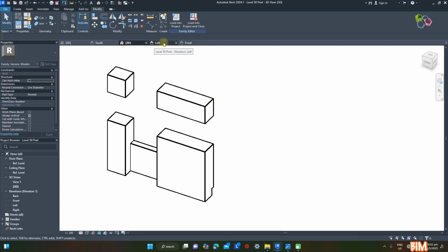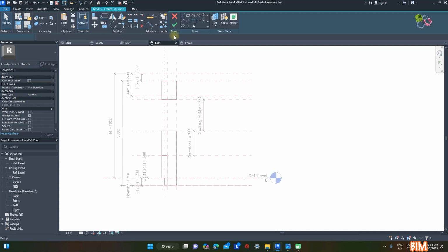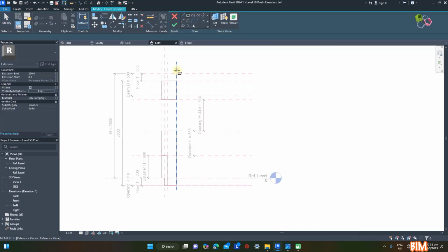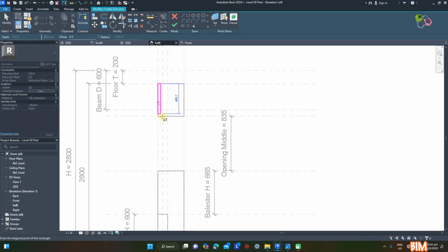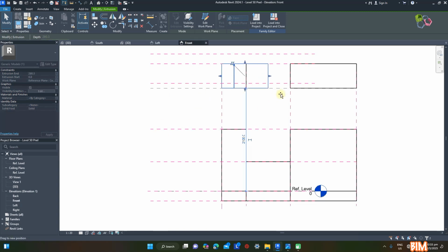We've a cut in the middle, but lost the existing recess for the middle component. So, we need to replace it back. To do this, create a solid component: create, solid form, we'll use the rectangle tool, top left to bottom right for the 150 mm middle plane, lock them all. Go to front elevation. Drag the shape handle of the solid component. Align to the middle 2 reference planes at left and right, locking is required for all.